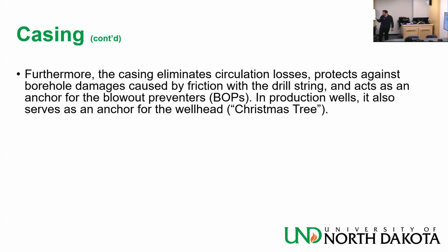During production, you have the Christmas tree. During stimulation, the company would bring their own tree, it's called the frac tree. During cementing, the company brings its own tree, it's called the cementing head, or cement tree. And that fits on top of the blowout preventers, actually.